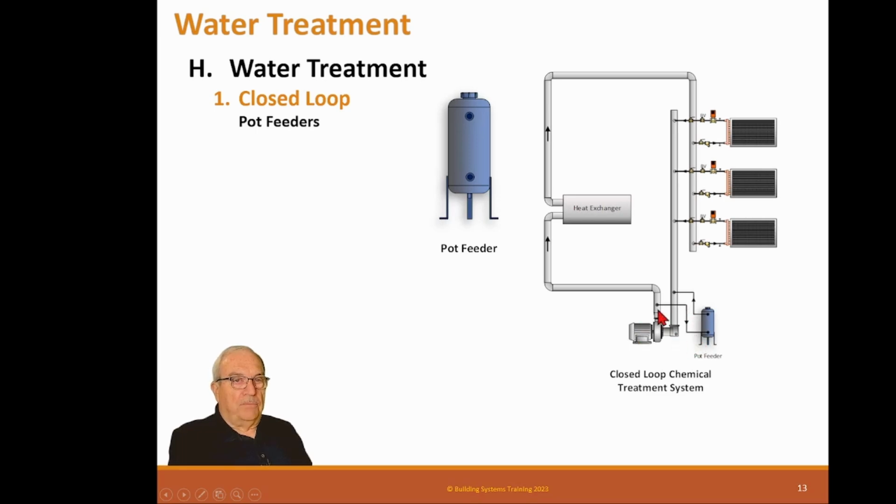So the pump is small pipe, 3/4 inch. It's running water around there to dissolve whatever you put in here to get it inside of this. And if you need to put a whole bunch in there, you just do it more than once. And then once you've got it established, the right chemical balance, which is normally like 1,000 to 1,200 parts per million, then you're done. You close it off and it runs.